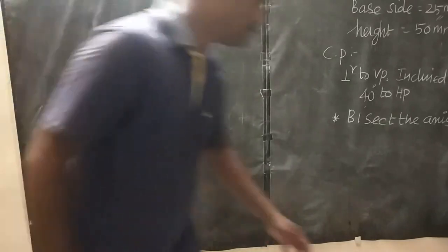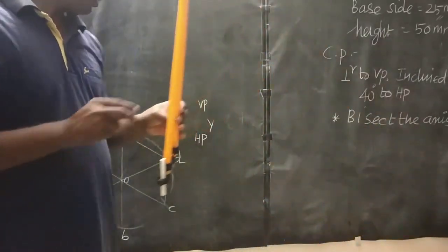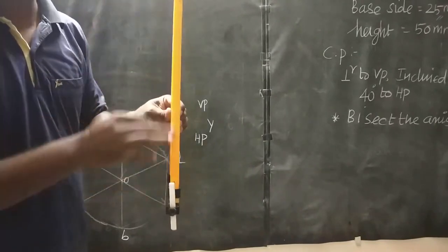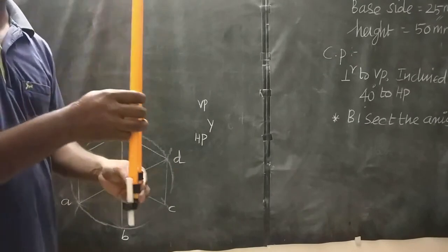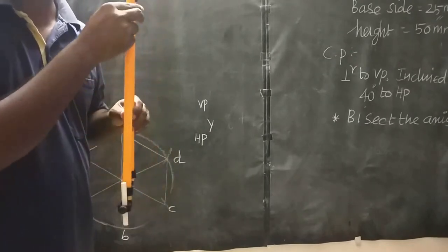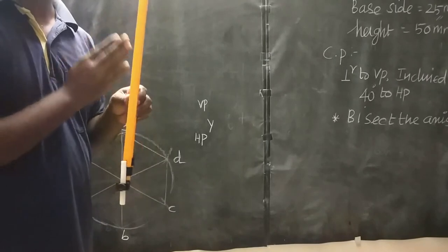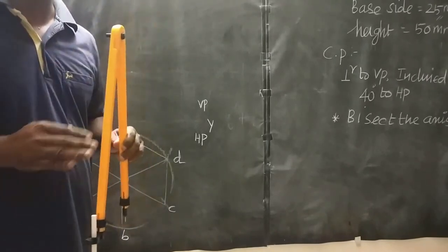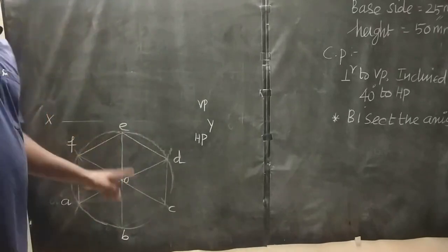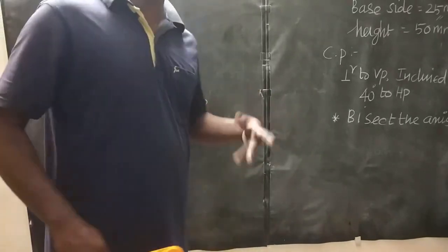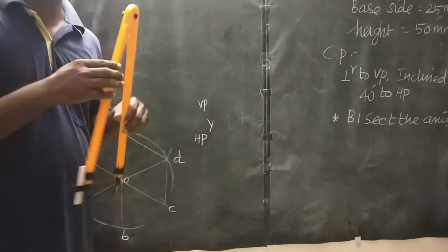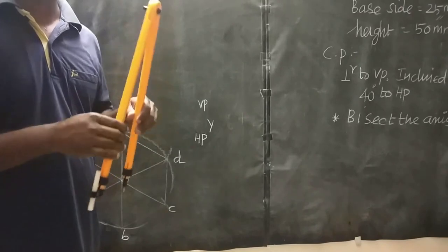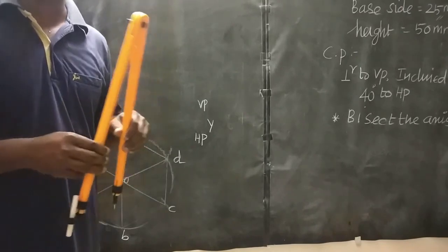The reason is that, see here. So this is the front slant edge, that is OB. This OB slant edge hides the axis. So in a front view, this slant edge is visible. Your axis is invisible. So give more priority to the visible boundary. So here draw the axis as a continuous thin line. But in some other problems, none of the slant edges hide the axis. That time use chain thin line to draw the axis.